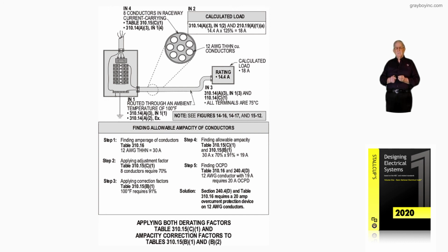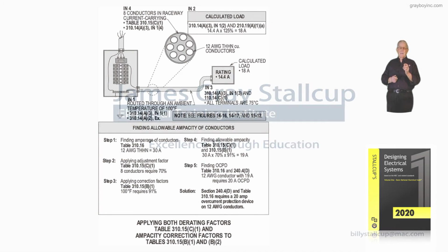Now, notice that the 52 amps is large enough to supply the 40 amps, but we had to use method 2 because the conductor produced by the calculation was greater than the calculation in method 1. So what this basically is illustrating is that feeders and branch circuits have to be sized in this manner in accordance with what is illustrated here in Figure 8-15B.